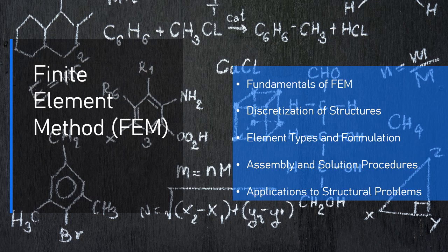FEM can be used to calculate the deflection at the point of loading, the distribution of bending moments, and the resulting stresses at various points along the beam. Benefits: ability to model non-uniform cross-sections. Nonlinear behaviors, such as large deflections or plastic deformation, can be accounted for. Can analyze the beam's dynamic response under time-dependent loads, e.g., vibrations.